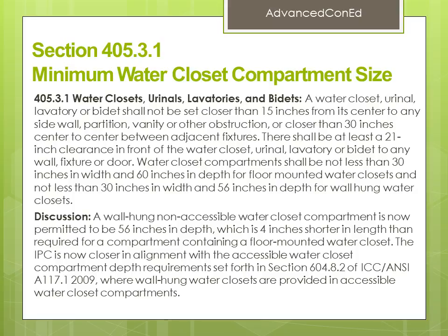405.3.1 Water closets, urinals, lavatories, and bidet. A water closet, urinal, lavatory, or bidet shall not be set closer than 15 inches from its center to any side wall, partition, vanity, or other obstruction, or closer than 30 inches center to center between adjacent fixtures.